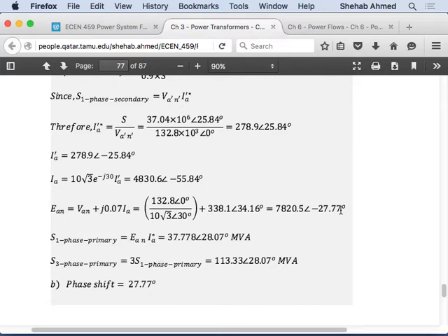So the wording of the problem is not very nice, but it covers everything we wanted to cover. It covers this star delta phase shifting. It covers the difference between the actual turns ratio and the terminal voltages in a star delta transformer. In a star star or a delta delta transformer, the ratio of the terminal voltage is the actual turns ratio. In a star delta transformer, the ratio of the terminal voltages is not the actual turns ratio of the physical transformer. Is this clear?